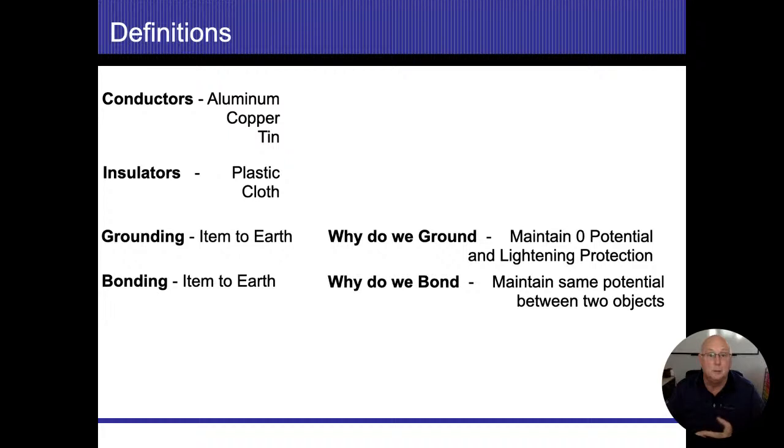They brought that to Underwriters Laboratory and a few other places where they did the testing, and then they started making changes into not allowing single-stranded aluminum or solid aluminum to be installed in any sort of houses. Now, here in the state of Illinois, it should be known that we do have mandatory defects that we have to report to our clients. There's only 5 of them, but one of those 5 is solid aluminum branch circuits.